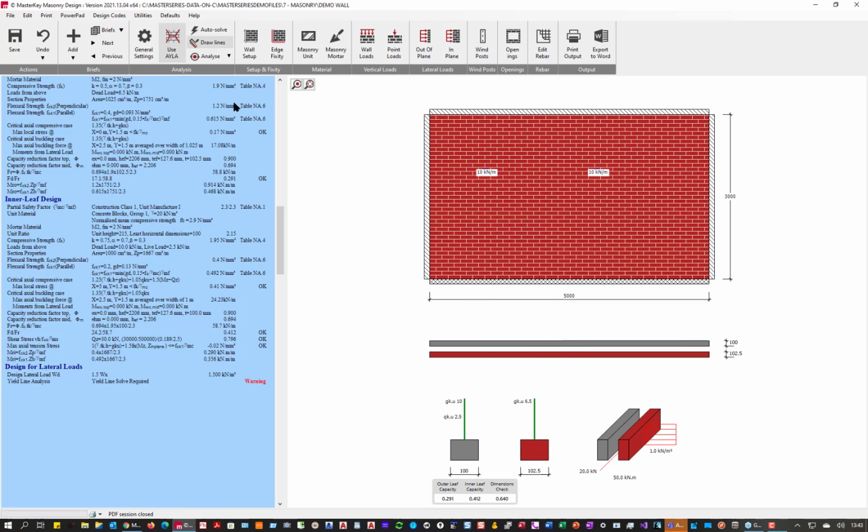So when I close it, and then I go analyze, it will now do the analysis with those 2 point loads. And even though it's supported the same all the way around, it's been attracted to where these point loads are to give you more, and it's failing miserably. And obviously bed reinforcement, thicker walls, stiffening, all that are the solutions to solve that.